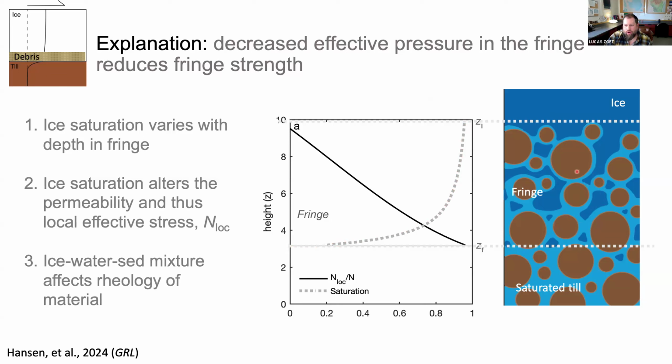Now imagine there's liquid water in here, which there is, and it has to move through this volume. If you start to choke up the pore spaces with ice, you make it harder for the water to move through the system. That changes the water pressure inside of this zone. It actually elevates the water pressure to a higher value than it would be outside of this zone.